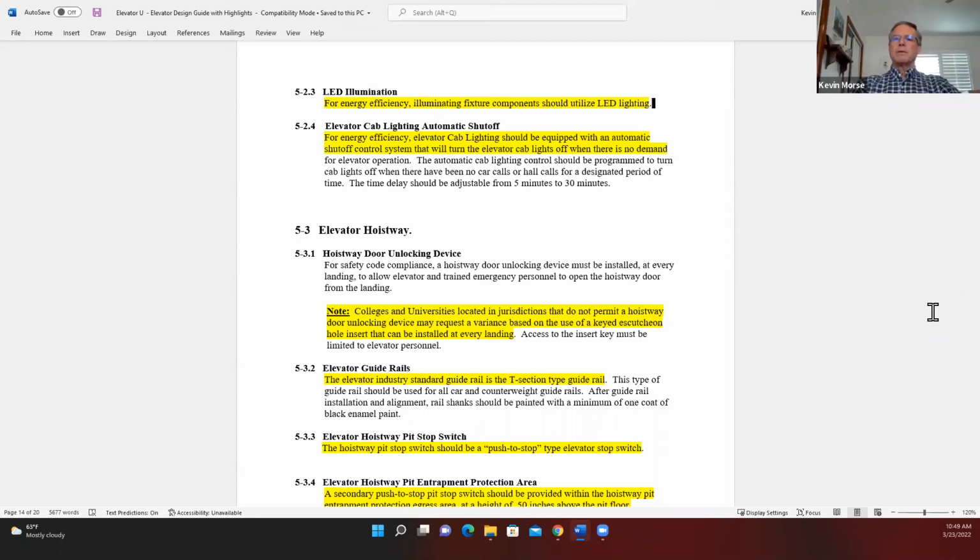Yeah, if you have a pit that deep, you probably would have a regular walk-in access door, not a ladder. I mean, the code, I think, used to allow a 120 inch deep pit. I think it's 144 now. So if the building design has a basement that the elevator doesn't go down to, absolutely, that's allowed by the code. That's not even addressed in this document. What's more typical is a pit with an access ladder. Yes, nothing in here precludes the use of a walk-in pit.